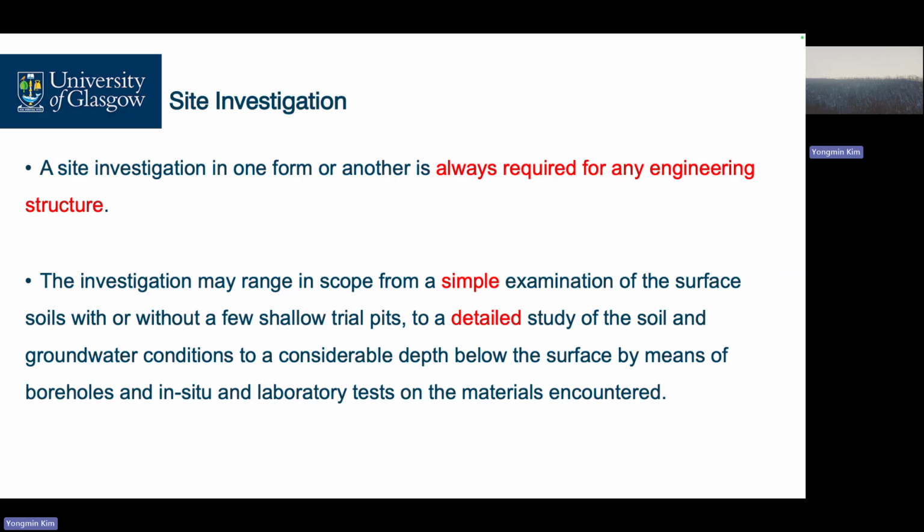Now it's time to answer the first part. Can you remember that our Hampton Hall building, 66 piles couldn't be in rock? It means the initial design expected rock socketed piles. It means expect high end bearing capacity. But with improper soil investigations, well, the majority is only friction.